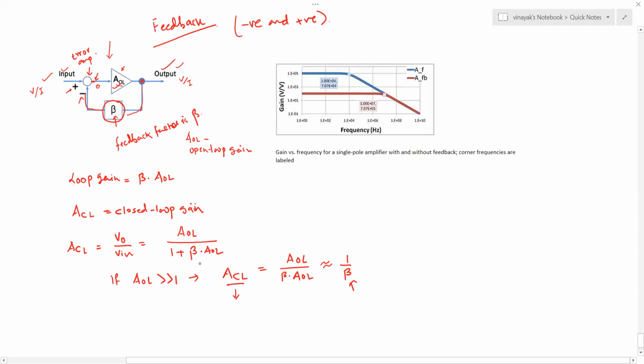Okay, and in amplifiers, we use negative feedback to enhance performance. That performance enhancement can be seen in terms of improving the linearity of the amplifier at the expense of reduced gain. So here I will say the pros of the feedback amplifier and the cons of employing the feedback. So reduced gain. The second is your bandwidth is going to be up. Okay, the gain here is down. The bandwidth is going to be up.